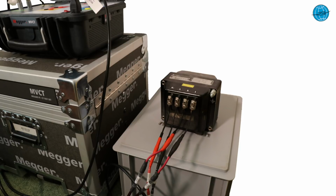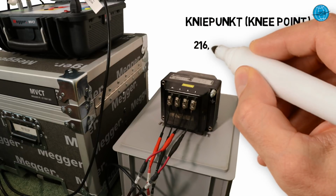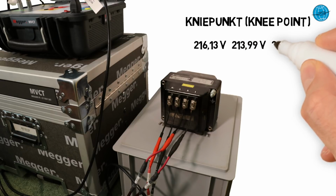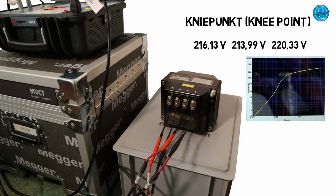The measurement of the saturation characteristic can be easily started after we have entered the nominal data of the CT and the corresponding test options. After a measuring time of 100 seconds each, the following results are available. For the startup CT, we were able to get knee point voltages of 216.13, 213.199 and 220.33 volts. In this measurement, only the magnetization characteristic of the device was determined and processed in a beautiful graphical